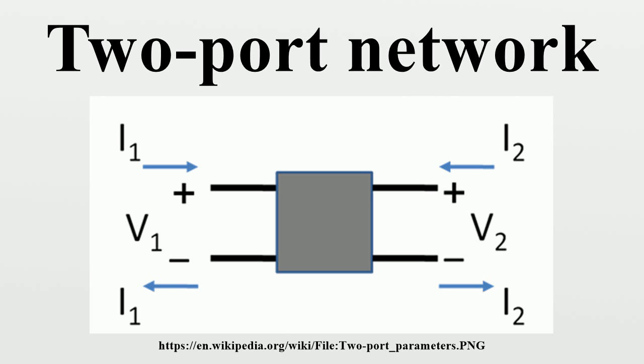transistors. Symmetrical networks. A network is symmetrical if its input impedance is equal to its output impedance. Most often, but not necessarily, symmetrical networks are also physically symmetrical. Sometimes also antimetrical networks are of interest. These are networks where the input and output impedances are the duals of each other. Lossless network. A lossless network is one which contains no resistors or other dissipative elements.